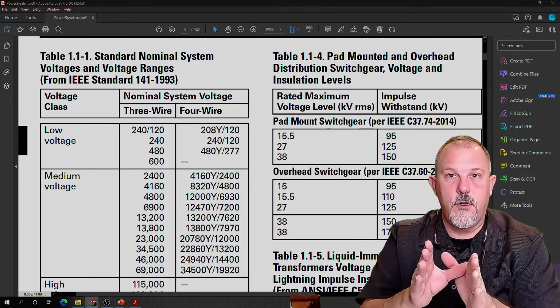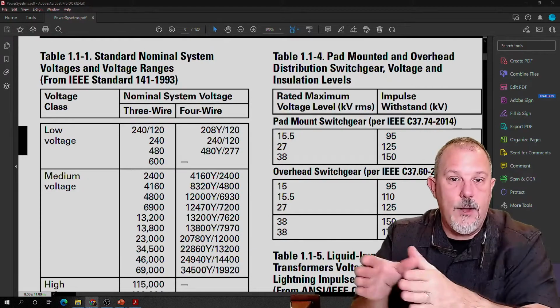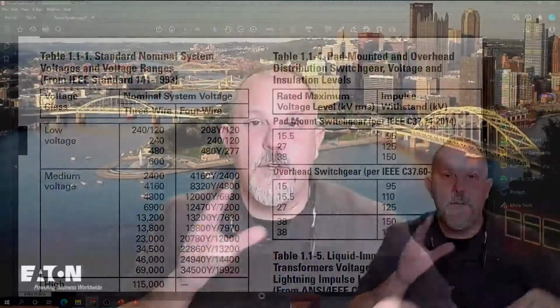is important. What's our goal? We have equipment that we have to operate. I want to make sure that it functions as designed. So my voltage at the terminals of my equipment is important. I can have a variance of voltage. I can have a maximum and a minimum voltage based upon power distribution system arrangement. What's turned on, what's turned off, what motors are starting.